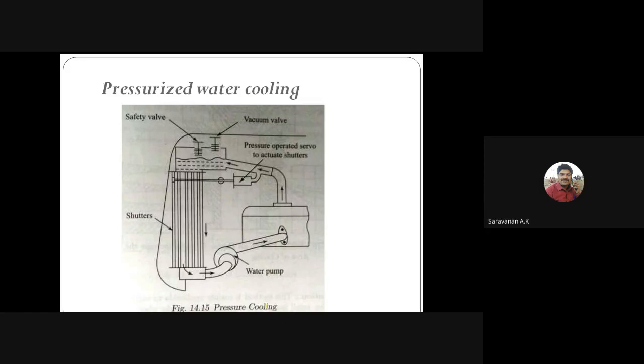We already mentioned that the rate of heat transfer depends upon the temperature difference between the two mediums, and the area exposed to the atmosphere. For air cooling, I already told that the heat transfer will be maximum if the surface area is maximum, which means the thermal conductivity will be high. So the fins' surface area being more means a good heat transfer rate. So the heat transfer rate depends upon the temperature difference between the two mediums, the area of the exposed surface and the conductivity of the material, and it may vary depending upon these.